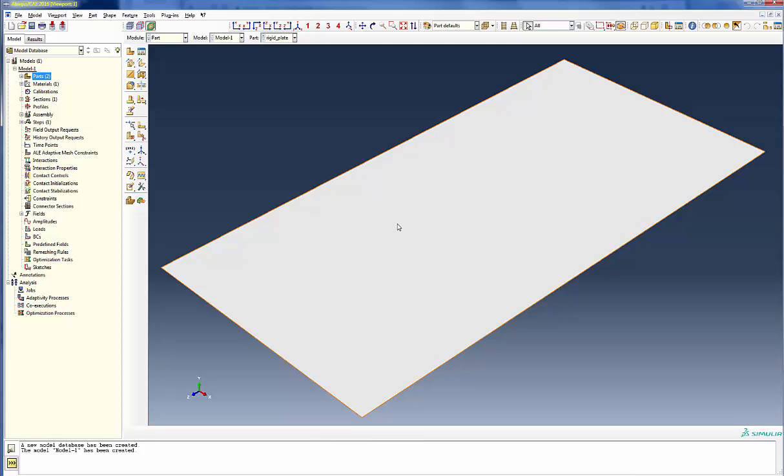We'll give it a reasonably large plate, so when the impact occurs, upon bouncing up and then the part wanting to fall over again, we don't want it to fall off the edge. We want it to fall onto the plate again, so it'll simulate the effect of bouncing on the ground multiple times. All right, with this in mind, we need to make sure we have a reference point on the analytical plate to be able to restrain that.